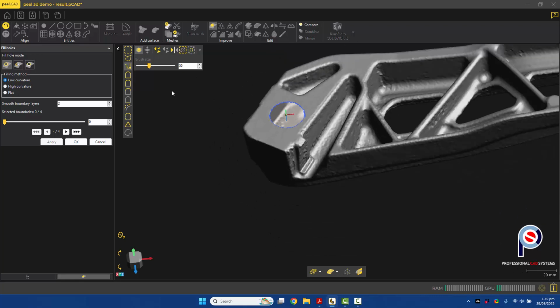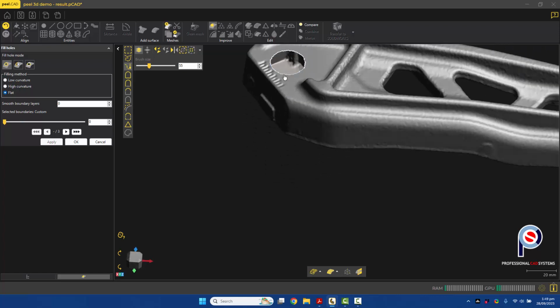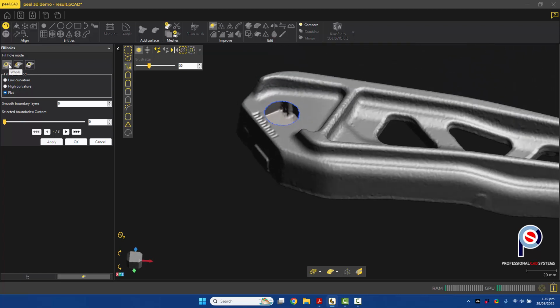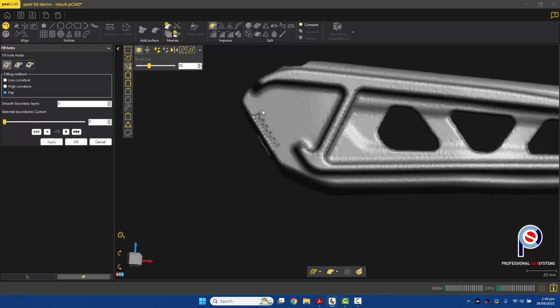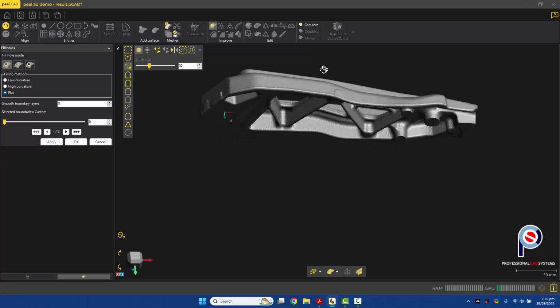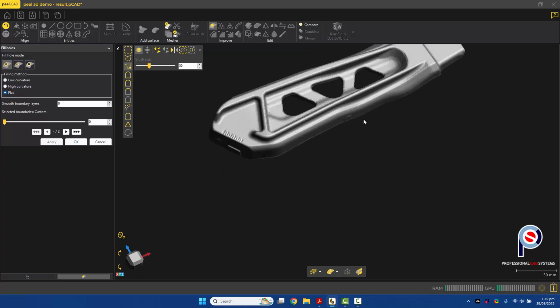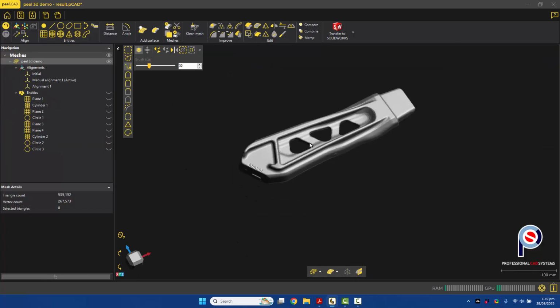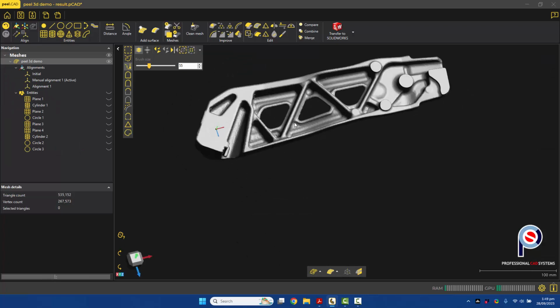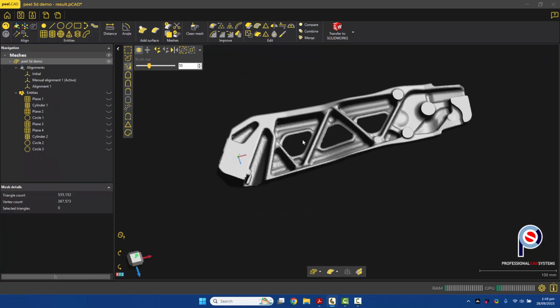And then we're going to switch that to a flat fill. So again, hole fill, flat fill, and just click on the boundary and just remove that. So we're making it more of a shape that we're going to then turn into a solid. And just removing these entities and then putting them back in CAD will give us more clean holes or bosses to work with.